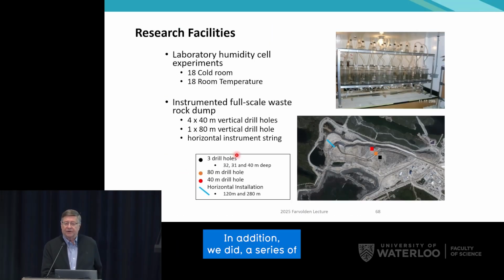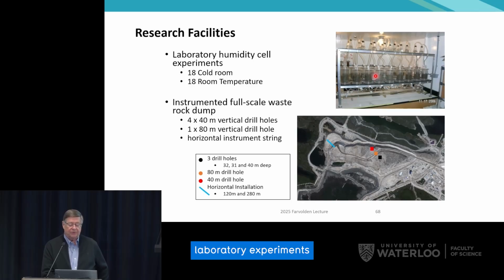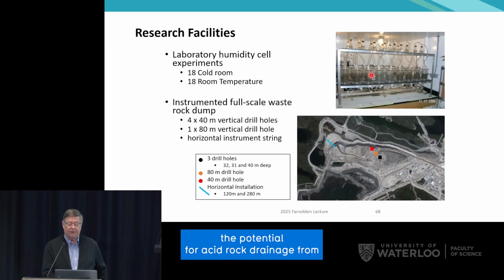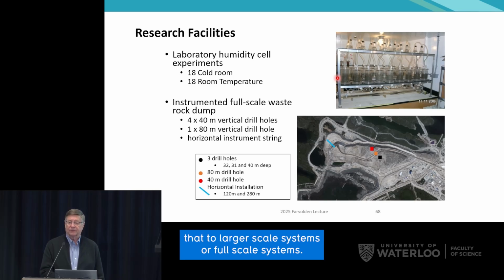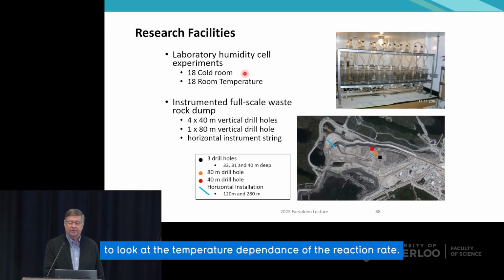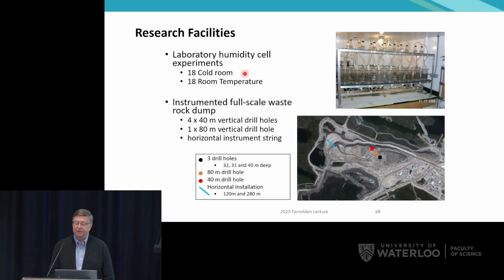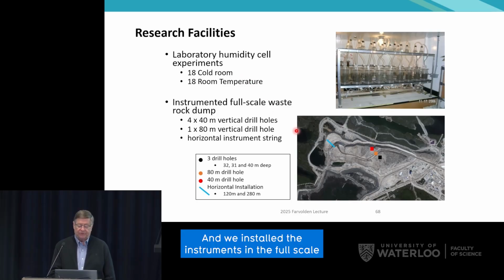In addition, we did a series of laboratory experiments based on a conventional technique that's used for evaluating the potential for acid rock drainage from mining companies, and part of the goal of that was to see if we could scale that to larger scale systems, or full-scale systems. So we did 18 of those experiments at room temperature and 8 in the cold room to look at the temperature dependence of the reaction rate. And we installed instruments in the full-scale waste rock pile as it was being constructed.